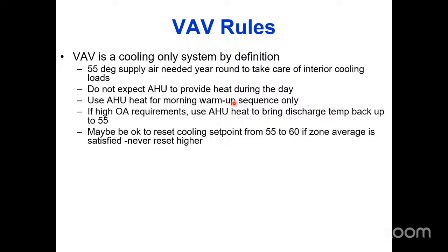Historically, we run that until a sensor in the return air duct warms up to about 68 degrees. And once it gets 68 degrees in the return duct, we say, okay, we're good. Shut it off. Switch over to cooling mode for the rest of the day. Here comes your 55-degree supply air. Let's go, right? That's what normally would happen.